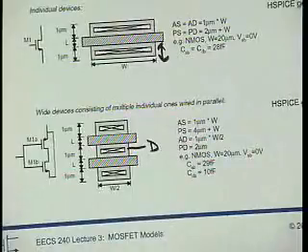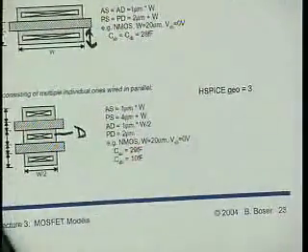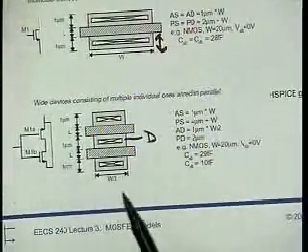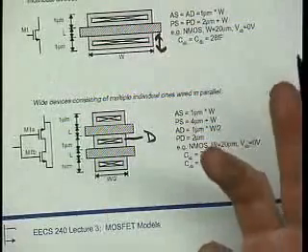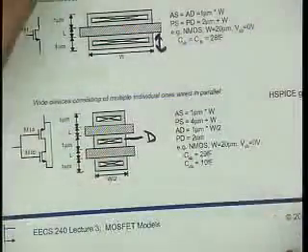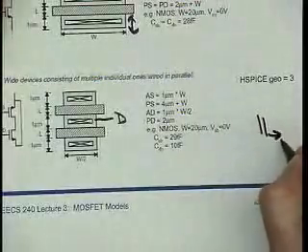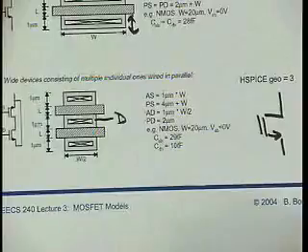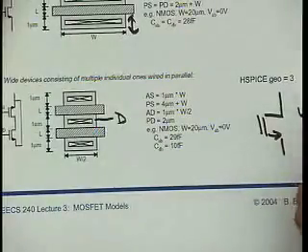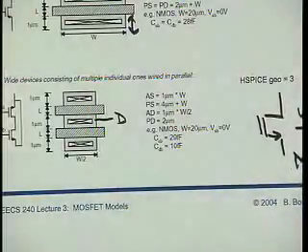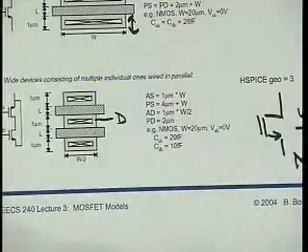So how do we specify that? Usually we don't draw something complicated like that in our schematic diagram, but we need to tell the layout person to use a finger transistor, right? And this is how many fingers you're going to use. So what we do is write down W over 2, the dimensions of just one finger, and then we also write next to it that we want to have 2 of these in parallel. And this nomenclature actually is even supported by SPICE.